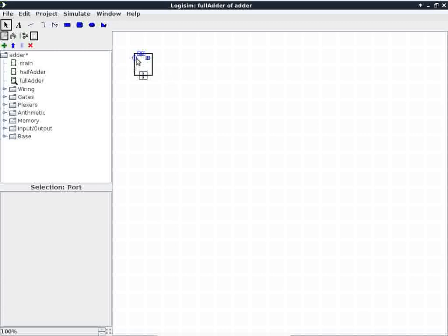the boundary. So the output carry goes here. Okay, that's fine. There's such a thing called an anchor. The anchor is not that important. All it does is specify, when you drag a new design into the main part of the window, the orientation and also how the design is dragged by your mouse pointer. So you can basically relocate the anchor all you want, and it doesn't really do a single thing to the logical part of the design.